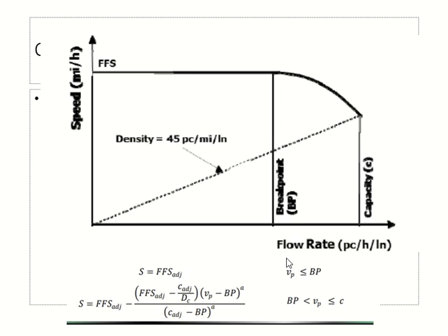Okay, this is called the speed flow curve, which we use for freeways as well as multi-lane highways. It starts from the free flow speed, then goes up to a point which we called earlier as practical capacity. In the graph they call it the break point. You can see up to the break point the speed does not change, but the flow is increasing. Drivers don't feel the need to change their speed up to this point, so they are still in free flow.